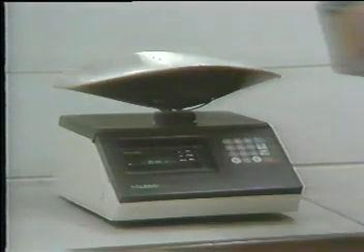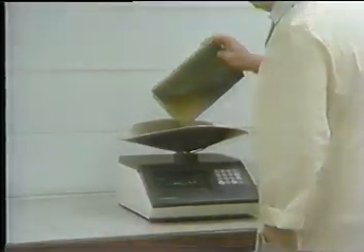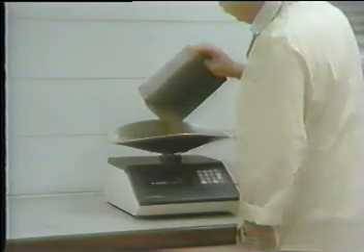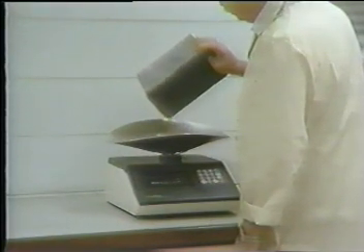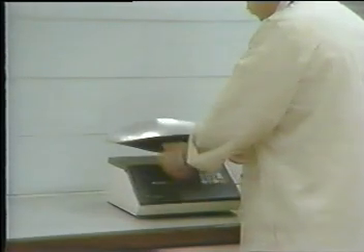After drying, the fine aggregate test samples should weigh approximately 100 grams when at least 95% passes the number 8 sieve, or approximately 500 grams when at least 85% passes the number 4 sieve and more than 5% is retained on the number 8 sieve.